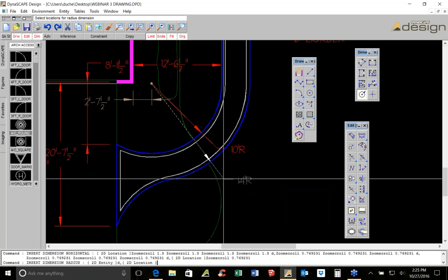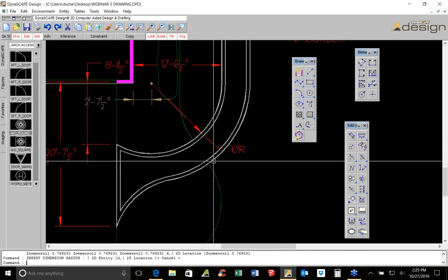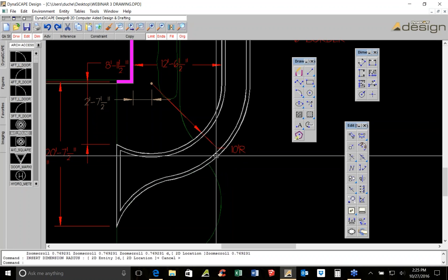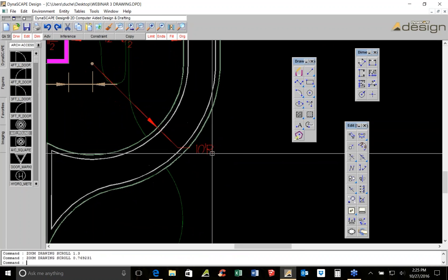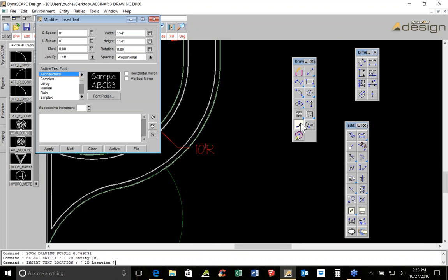So the best way to do this walkway would be to extend that tape another 4 feet and do this again. Now, you really want to do like a 6 to 12-inch over dig anyways and over base it so everything is secure. So maybe you would put a 10-foot radius, and then plus whatever your over dig is, whether you do 6-inch over dig.